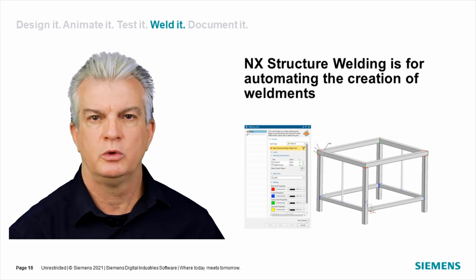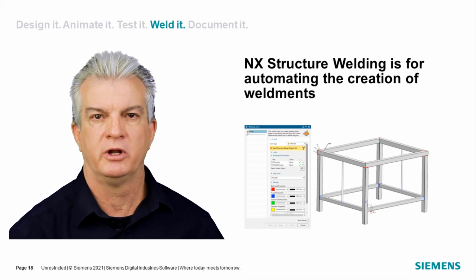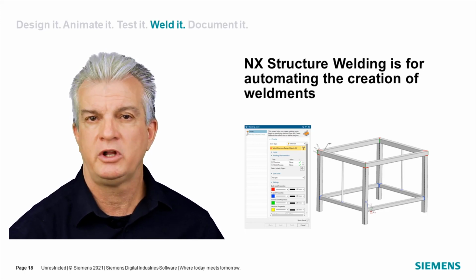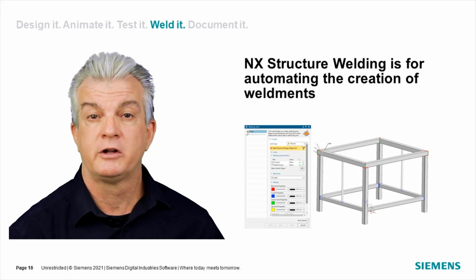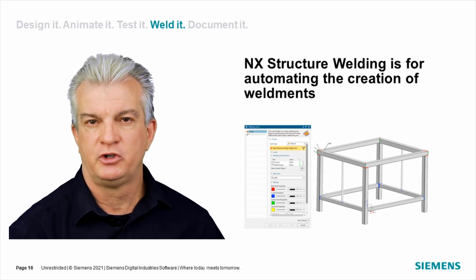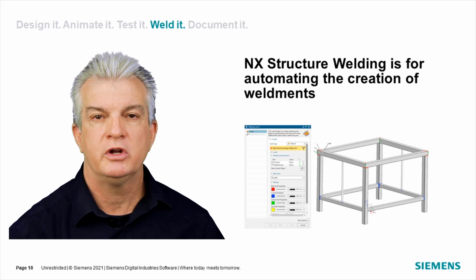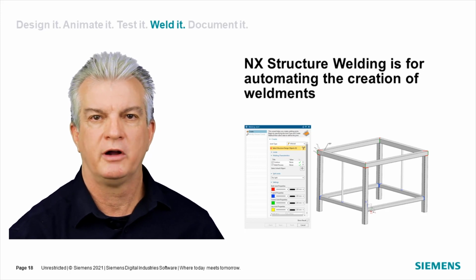Most people jump right to a drawing and annotate it with the weld information because the beads are just too time-consuming to put on. The integration that we have between NX Structure Designer and Structure Welding is totally automated. We define where the welds go during design and just recall and double check those in the welding application. You can create beads if you want to, but the goal is to go right to the PMI step and annotate your model. And you can use the weld information to drive a robotic process.